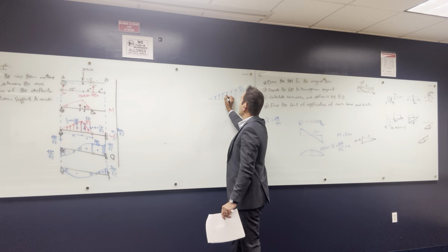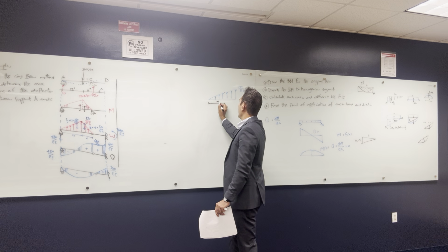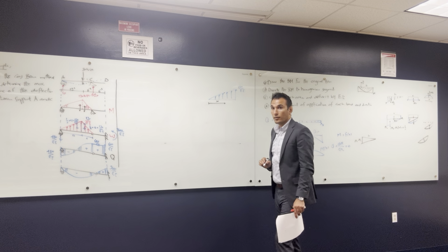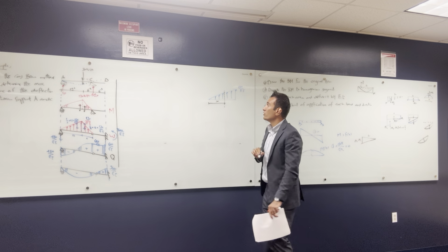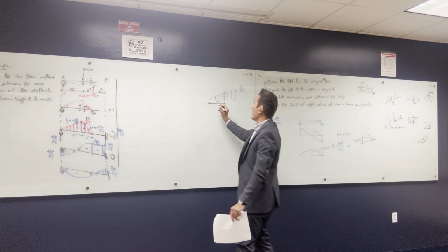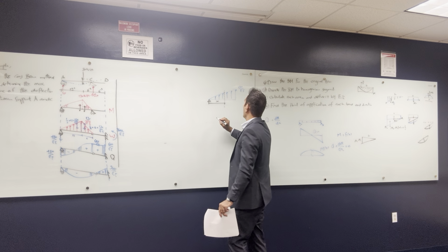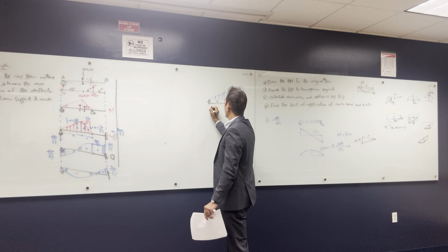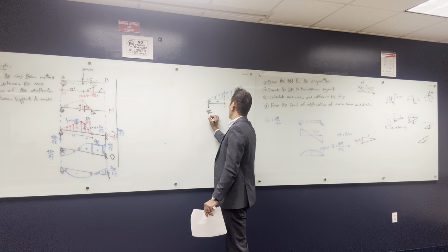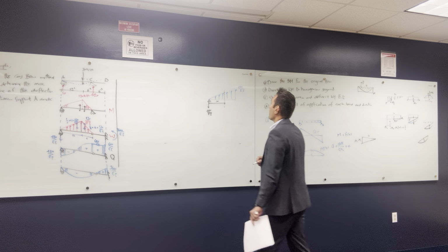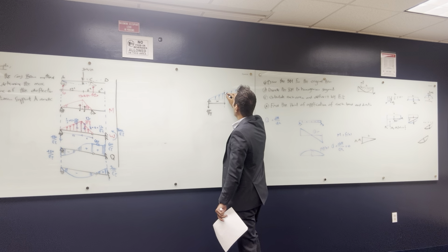So if I said that the shear is 0 at a point X, like let's say this is the point X here, okay? And I said that I can assume at this point that's where the shear is 0. And I have a reaction here, I have a roller, and I have nothing here, and I have a reaction here going down, it's 480 over EI. Okay? All right, so I want to find what is the value of the load here.